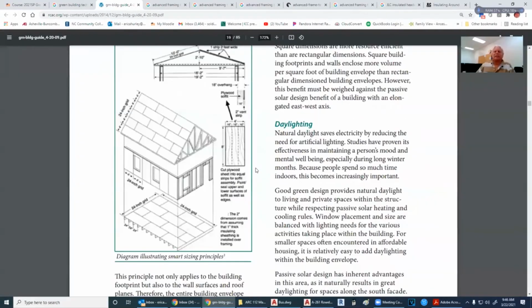They're talking about 24-inch grids and stacking it, so everything is stackable right on top of each other. We've got floor joists, studs, trusses, everything stacked in a perfect line. It takes a lot of thinking to do this. You're talking about buying the 2x6s and putting them at 16 inches on center.